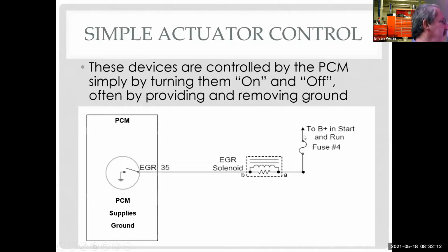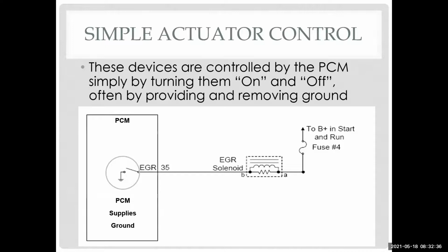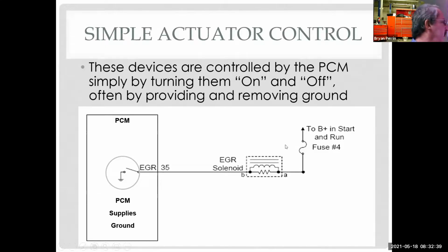So in this case, I have a fuse, I have a solenoid, goes to a computer at pin 35 and goes inside to a transistor, which is my switch. So with the circuit in its current position, what voltage would I see at pin 35? You should see battery voltage potential, right? Absolutely. I should see system voltage potential, because I have system voltage. It's gone through the resistor all the way here, all the way to an open circuit. In an open circuit, I can't use any of that potential. So therefore, I would see system voltage on my meter here.